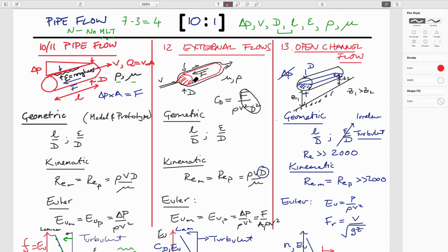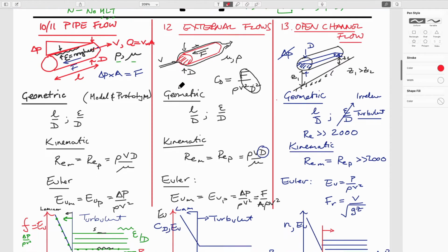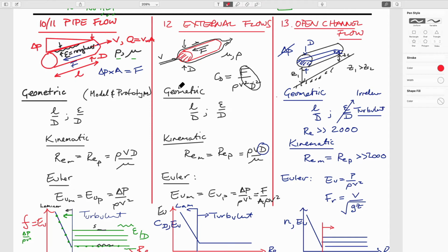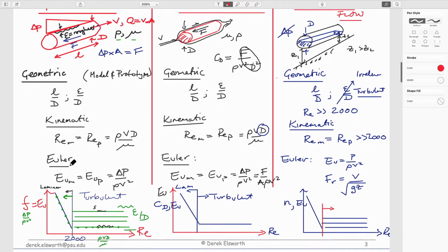And the 2 mechanisms would be shear drag by viscosity on the side, and also the kind of full frontal force acting on your chest, which is different from the force that's acting on your back, the stagnation stuff like the truck on the San Francisco airport tarmac. And so those 2 components of drag are really what we've seen here.